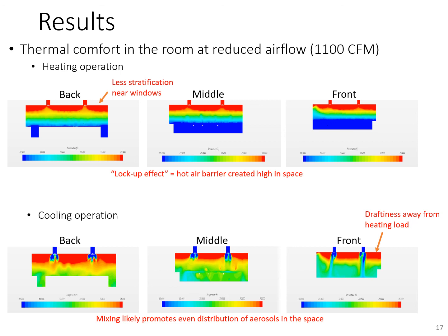Thus, it was determined that the recommendation for modifying the airflow provided to the space may be seasonal in nature. Instead, it might be advantageous to use other methods of viral spread prevention to limit deviation of the HVAC system from its original design intent. However, these recommendations are not all-encompassing for all facilities, as each space in a building will promote different airflow patterns based on the layout of the rooms and locations of supply diffusers and return grills.